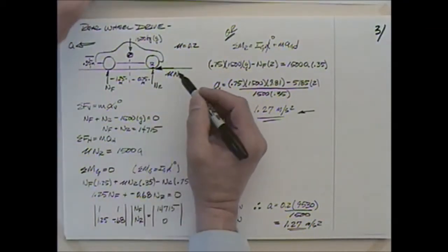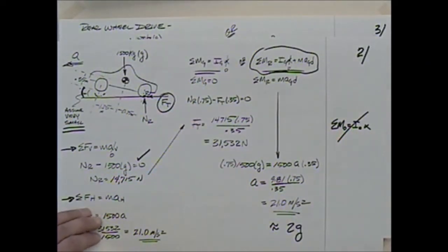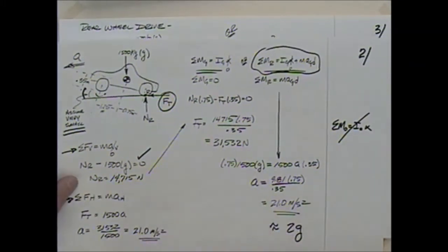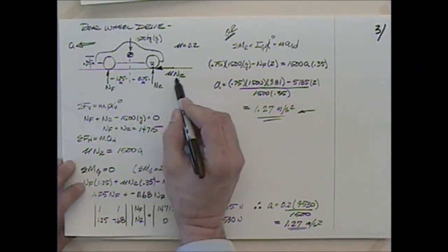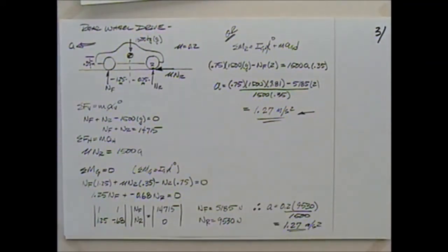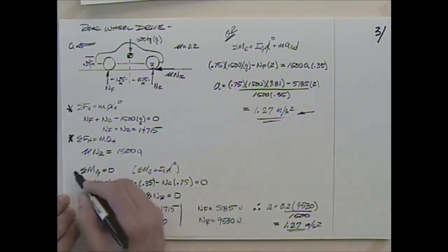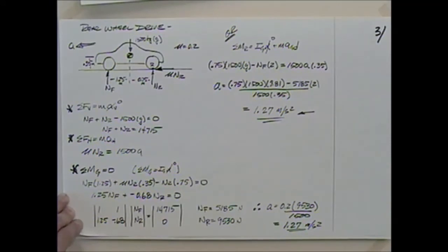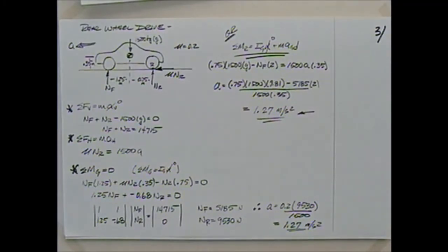You'll see that in the previous case, when I had the wheel stand, I talked about the tractive force, and I didn't say that that was equal to the coefficient of friction times the normal force, because it's not. It's probably not up to that value yet. And here I'm going to say that the friction is fully developed, and I have mu times the normal force at the rear. I didn't look at the four-wheel drive case like your homework problem did. I just looked at the rear case, and I'm going to go into this in some more detail. I used, again, sum of the forces in the vertical, sum of the forces in the horizontal, and then I used my sum of the moments about G. You could, if you wanted to, come back and use this equation. Probably in this one, that equation is again a little bit easier.